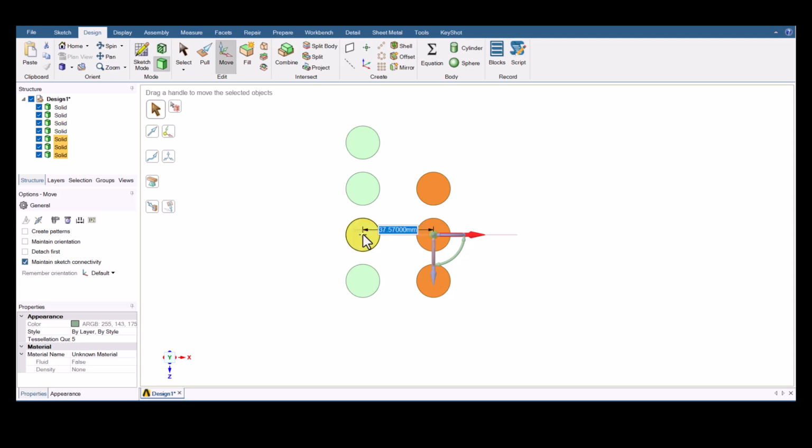You can keep the distance between the cells as per your own battery pack assembly. Arrange them in 4 staggered rows with alternating 4 and 3 cell configurations. This arrangement allows airflow channels between cells.